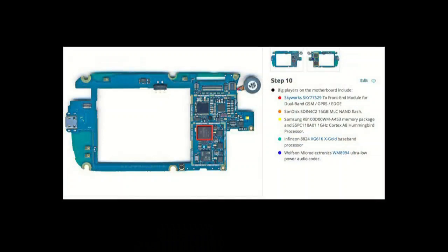And one thing that we were told very early on was that we had to hardware disable the cellular phone functionality of the phone, for the same reason that when you get on an airplane, you have to either put it in airplane mode or physically turn it off. It turns out the ISS has similar rules, and it's pretty much all the time. It needs to be in airplane mode. And we told them, well, in the kernel, we can completely disable the phone's ability to talk to the radio. We'll guarantee that there's no way that this radio can be activated. And unfortunately, the comeback was, well, no, actually, it needs to be a hardware disable. You have to have a hardware switch or some way of physically making sure that transmitter can never fire up.